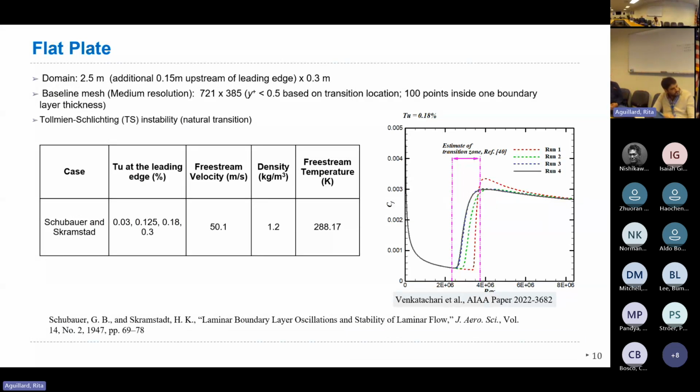That's more important for hypersonics. Ethan Vogel within the group is looking at that. I think he had a presentation not too long ago, last presented at SciTech, and he's been working on that especially to pick that transition. In the past, people have approached it in different ways. One way, I think Arnal had predicted, instead of limiting intermittency to being 1, you temporarily allow it to go beyond 1. That way you would get the peak, but you couldn't anchor it to any particular experiment, and you would have to tweak it. He had some analysis for that, but it's not very robust.